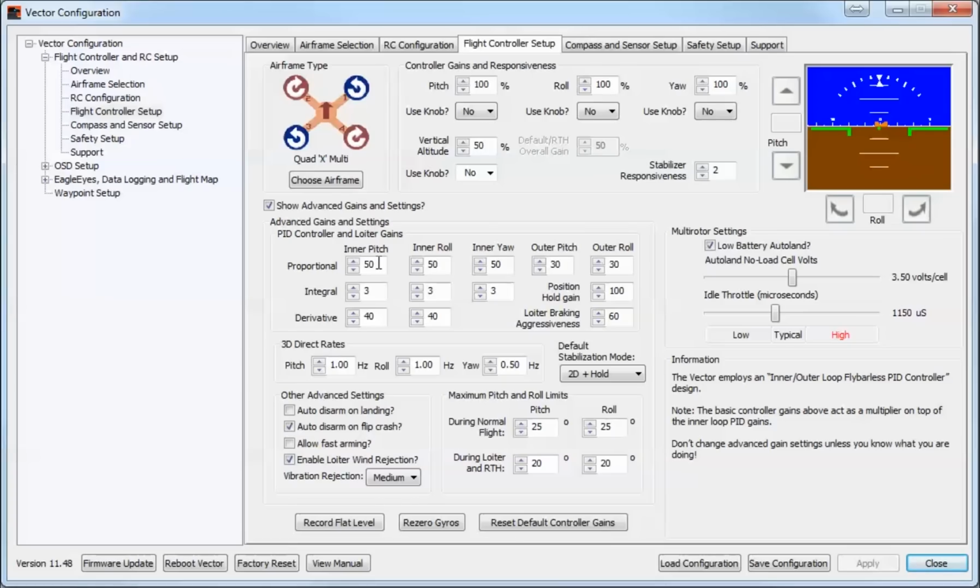There are settings that you can change if you've got a very strange CG, or if you've got potentially a dead cat and you found that the yaw wasn't working right because the trigonometry between the motors was slightly off, like you can adjust with the KK2 board. These are places that you can do it, but I don't have the expertise, and I would strongly suggest if you're going to look at this, go to the forums, ask the questions, get advice from people who have actually played around with it. Generally speaking, you're not going to do it.